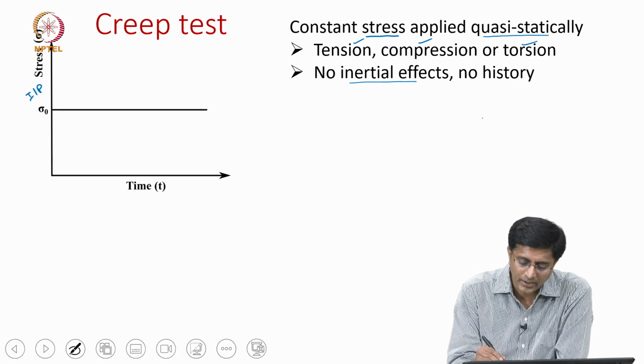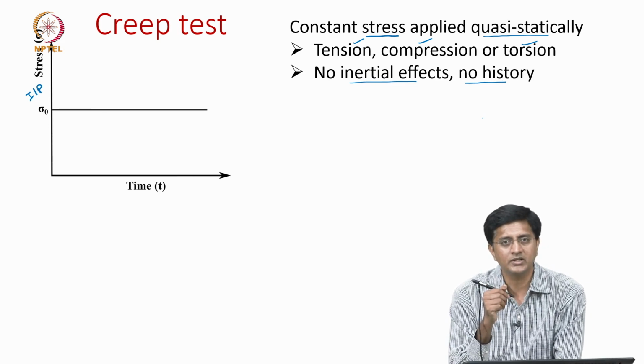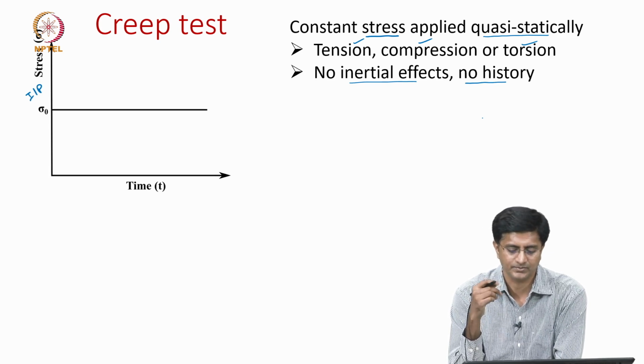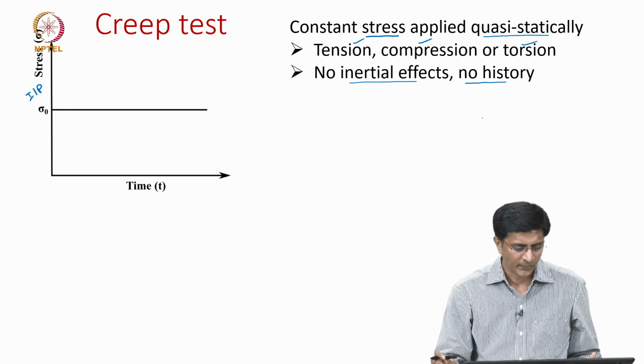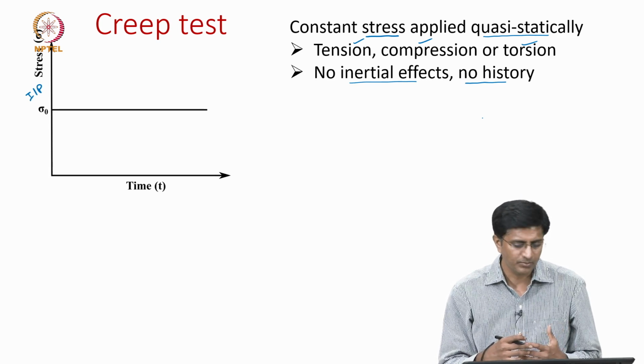And again I need to mention that care should be taken with the specimen so that there is no loading history, or if there is any loading history, there is some mechanism by which we try to remove that history, either through annealing or other means. But now let us see what is the response for this creep load.